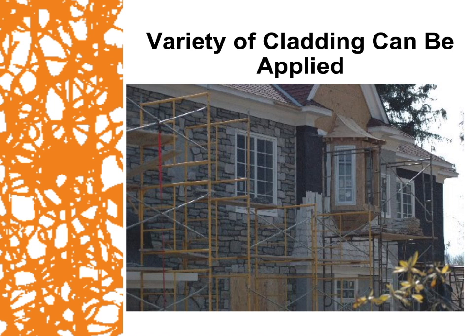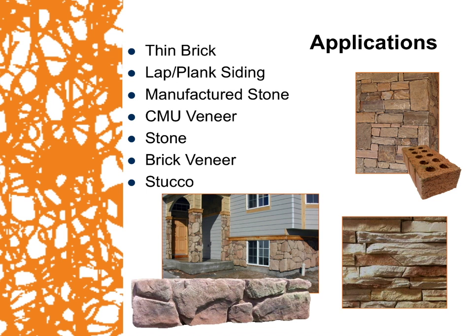You also want to ensure that it can handle a variety of cladding. Just like in the picture in front of you, typical projects don't just use one type of facade or cladding. We use multiple, typically brick and siding, a little bit of stucco, or siding, maybe some cedar shake with some natural stone. We like to mix and match our facades, and so ensuring that a product behind it is monolithic, that can handle that transition and having multiple claddings on top, so that you don't have to worry about changing different products and doing different things behind each different facade.